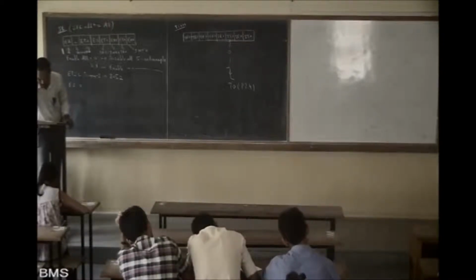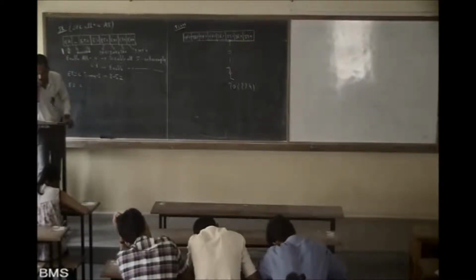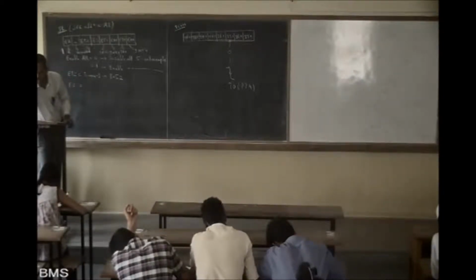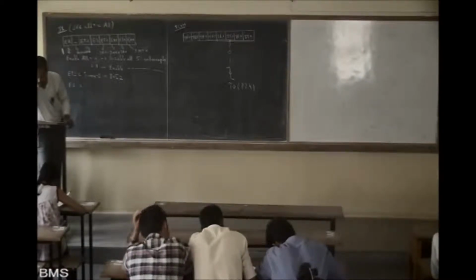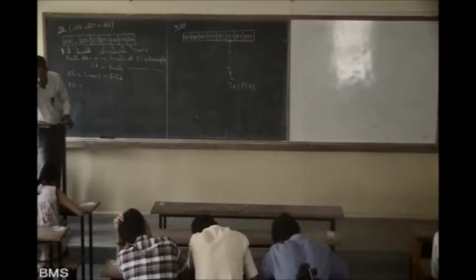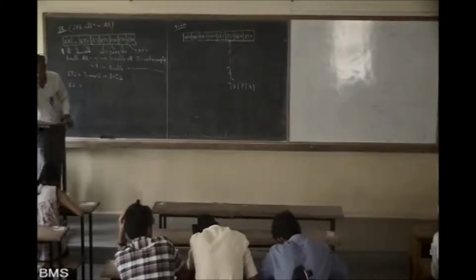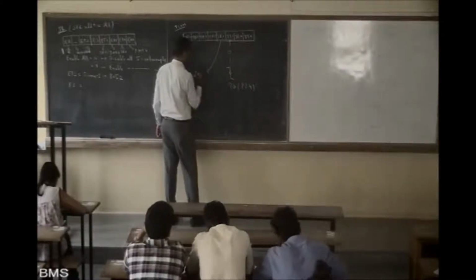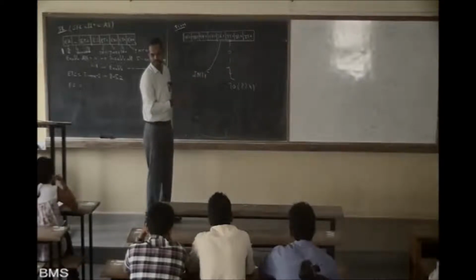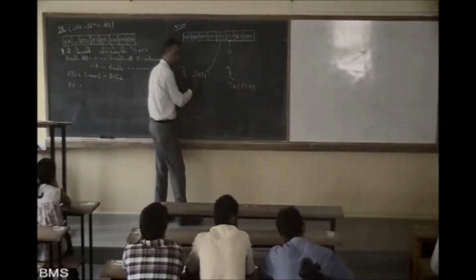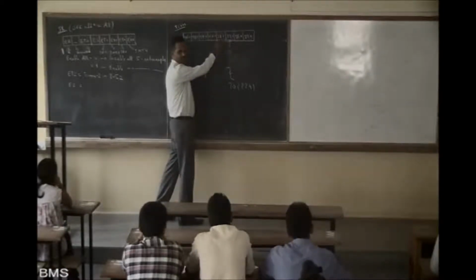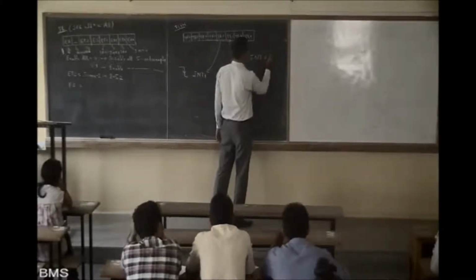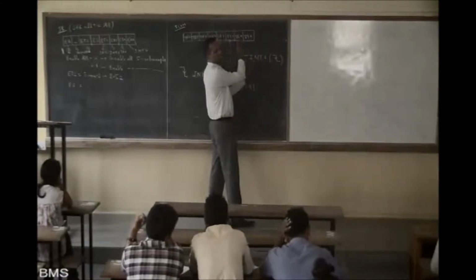Below that, write a note. This flag does not latch low level triggered interrupts. That is why we called it the edge flag. This IE1 is the INT1 interrupt edge flag. Whenever there is a high to low signal on INT1, this will set. For IE0, it is the INT0 flag. Whenever there is a high to low signal on INT0, this will set.